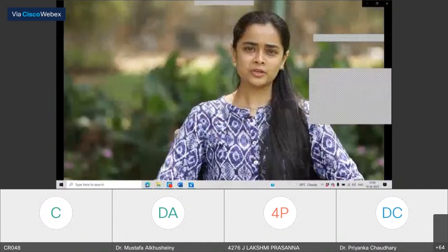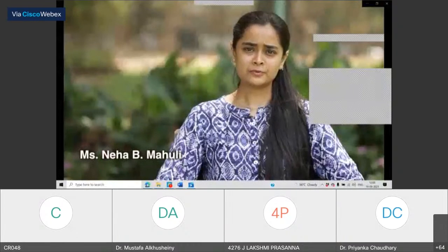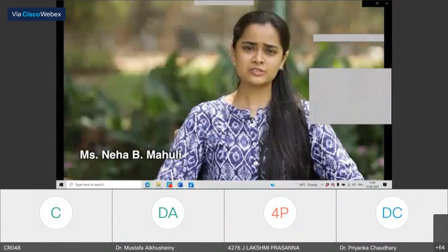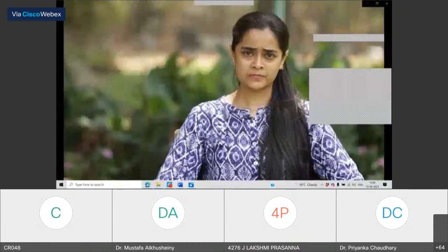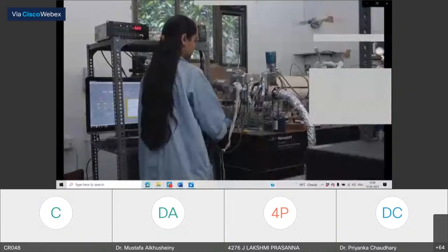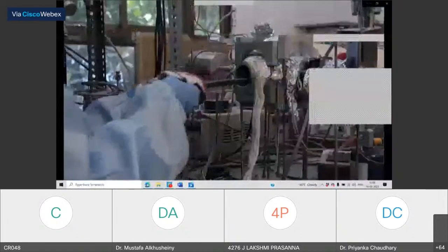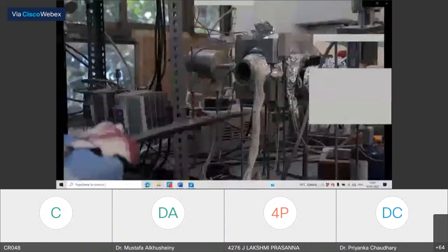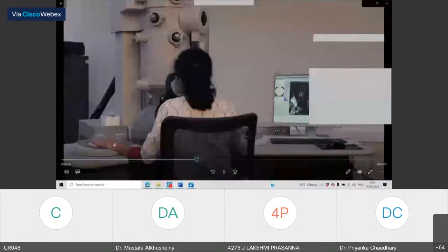We work on economically viable thin film solar cells. Our main focus is to develop new materials that can harvest solar energy by depositing layers of atoms one by one. In order to study various aspects of these thin films, like quality of the film, its elemental analysis, and its abrupt junctions, we need highly sophisticated techniques like TOF-SIMS and HRTEM.